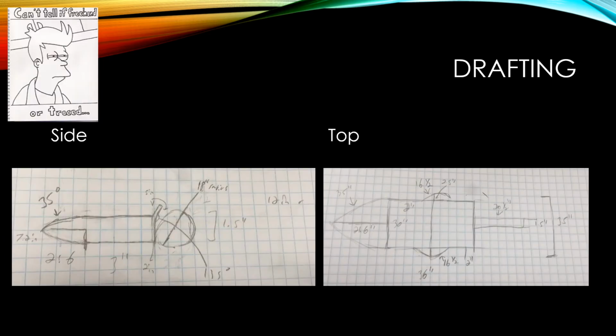Seen here are the rough sketches for our initial design of our partial fairing. As you can see, it's more like a front cone is being placed on the trike itself, with that back circle being the rear drive wheel. What this does is it shapes up the front to where it's easier for the air to flow around it. It's more consistent and we'll have a smoother flow pattern, but we're only using partial for ease of design and to make transitioning riders a little bit easier on ourselves during the competition.